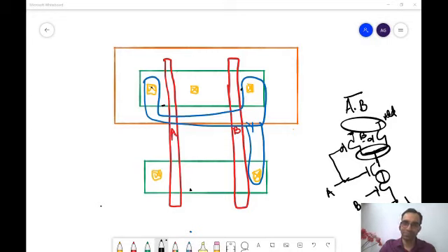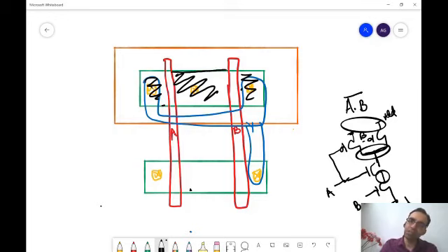Sir, one of the LS parts gets eliminated if we do the middle tapping. So only one inversion layer gets eliminated. So basically two inversion layers will come here, right, sir? So only one LS gets eliminated, or both the LS, both the widths get eliminated? See, even if you tell me that this area is the same as this area, what happens? There is a sidewall junction capacitance also, which is appearing only for this side here, but in this region, it is appearing for all three sides.